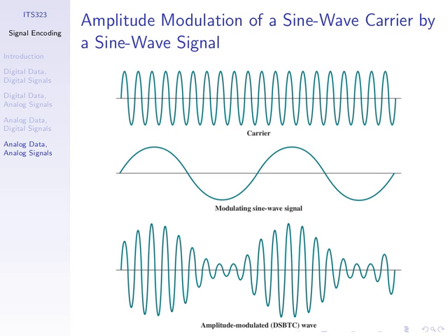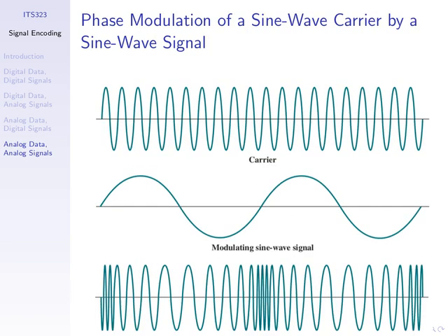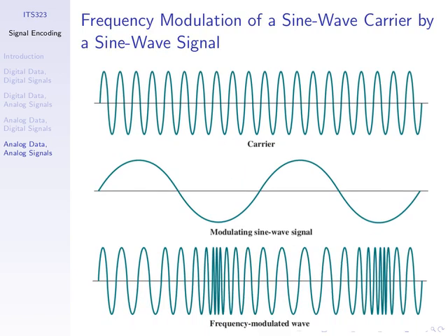This is generated from combining these two, in that we take our carrier signal, and with amplitude modulation, we change the amplitude of the carrier as the amplitude of the input data changes. When we've got a high value here, we've got a high amplitude of our carrier, and the low value, we've got a low amplitude of our carrier. So you can see the shape here, the amplitude of the carrier matches the amplitude of the input data. That's amplitude modulation. So the input data, the carrier signal, the output signal. And the other two are similar. Phase modulation and frequency modulation.